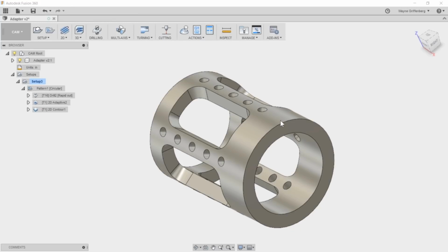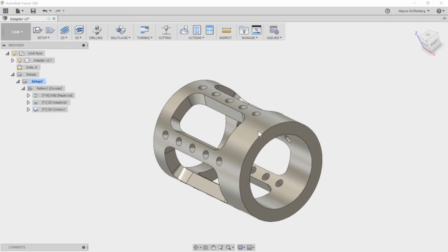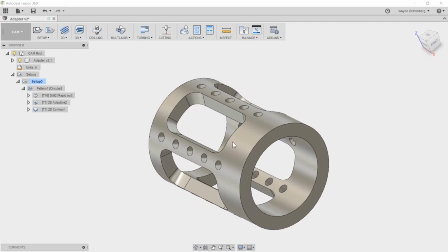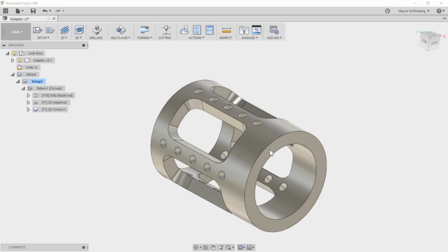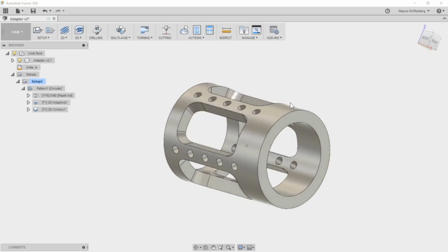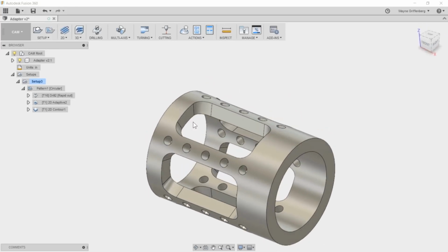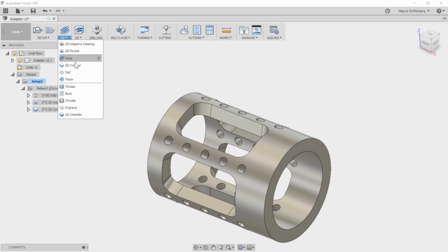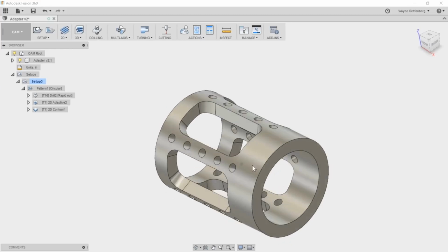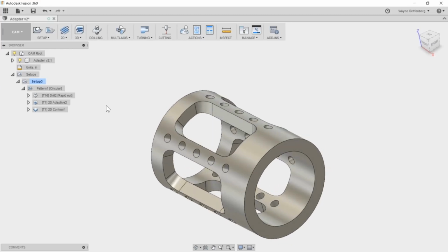Again, it doesn't have to be a cylindrical part. You can always do this on, say, a two-sided part to save your setups. You just do a top side, rotate it 180, and then do the bottom side. So it really saves you a lot of setup if you can do that on your rotary machine. But I really just want to highlight simultaneous fourth axis and being able to do indexing. So I don't know if you guys have any questions. I don't really want to go too far past the time, but I hope this has been helpful for you guys.